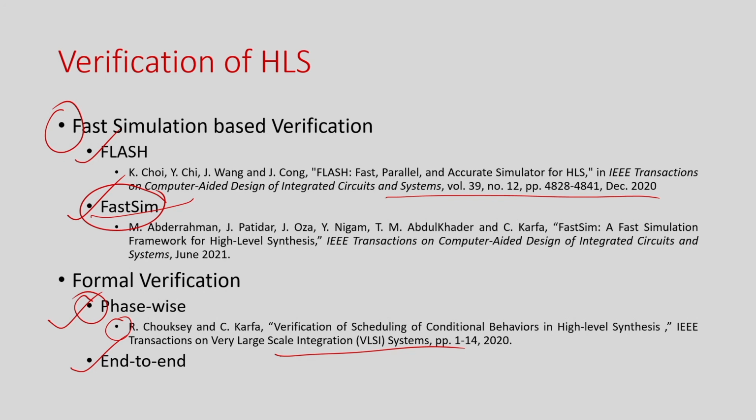I have already covered the basic intuition of FastSim. Basically you have an RTL to C converter, which I have already discussed in this class, and with that we can show that we can do this simulation based verification of high level synthesis very fast. So, this is all about the verification of high level synthesis.